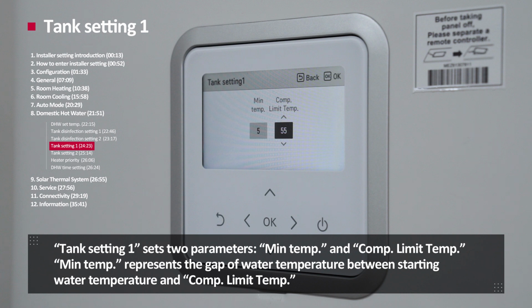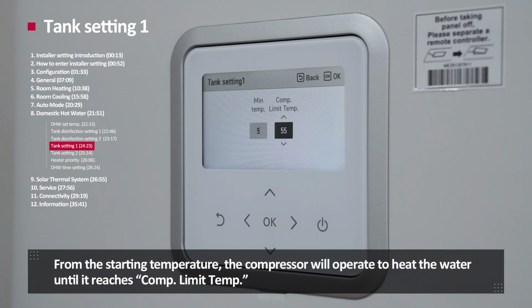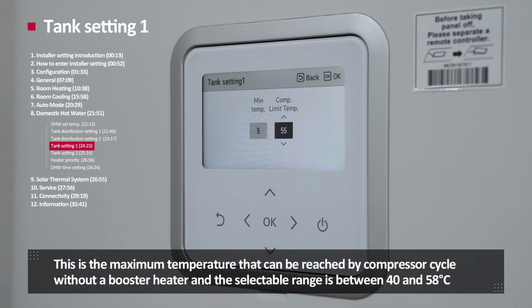Minimum temperature represents the gap of water temperature between starting water temperature and comp limit temperature. This value can be selected from 1 to 30 degrees Celsius. From the starting temperature, the compressor will operate to heat the water until it reaches comp limit temperature. This is the maximum temperature that can be reached by a compressor cycle without a booster heater, and the selectable range is between 40 and 58 degrees Celsius.